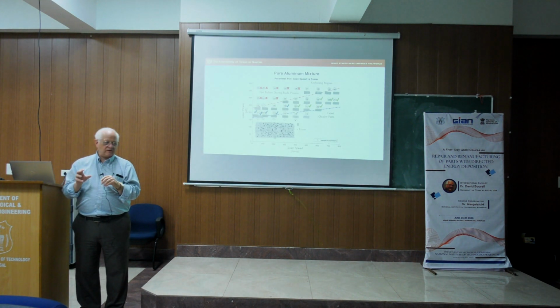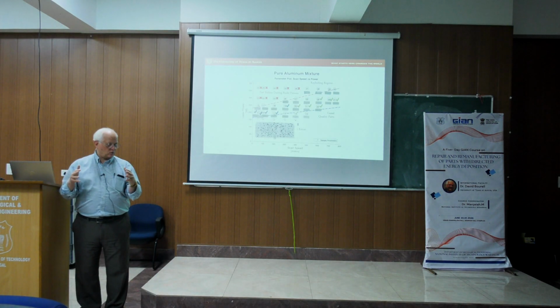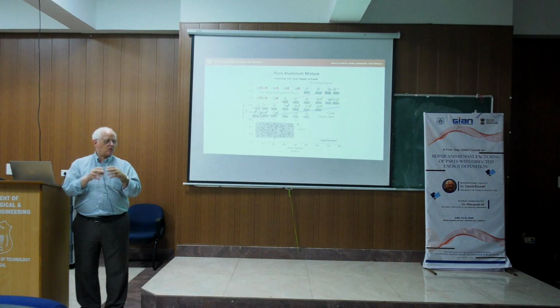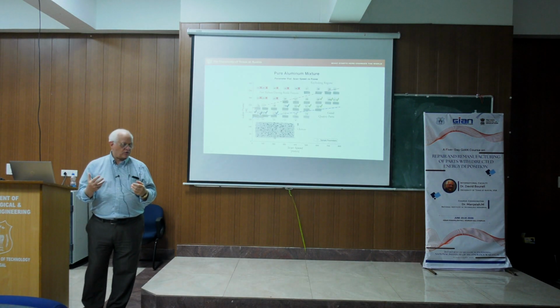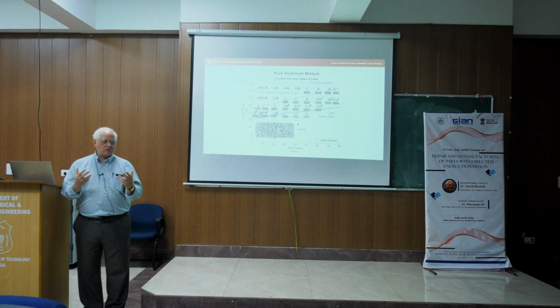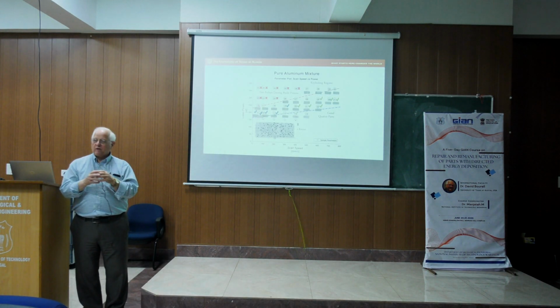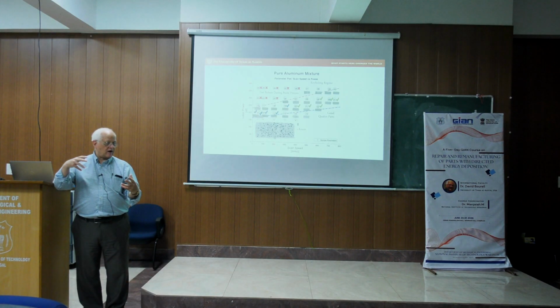One is the rate of grain growth once a particle forms. The other is the rate of nucleation of particles from the melt. So there's a nucleation rate and a growth rate, and depending on how those rates interact with each other, we can produce either a columnar type structure or an equiaxed structure.